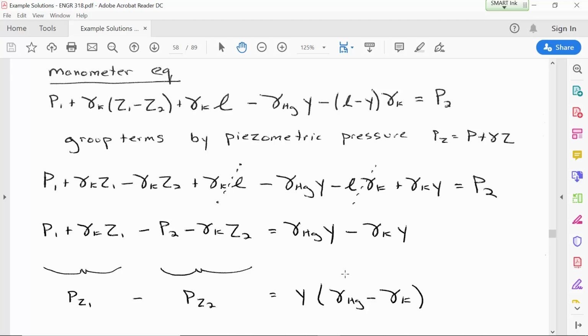And so here's just another differential manometer. Let's say it's full of fluid, but the velocity is 0. If there's no flow going through the pipe, then it's level. But as soon as fluid starts going through the pipe, the downstream segment is going to have less pressure.